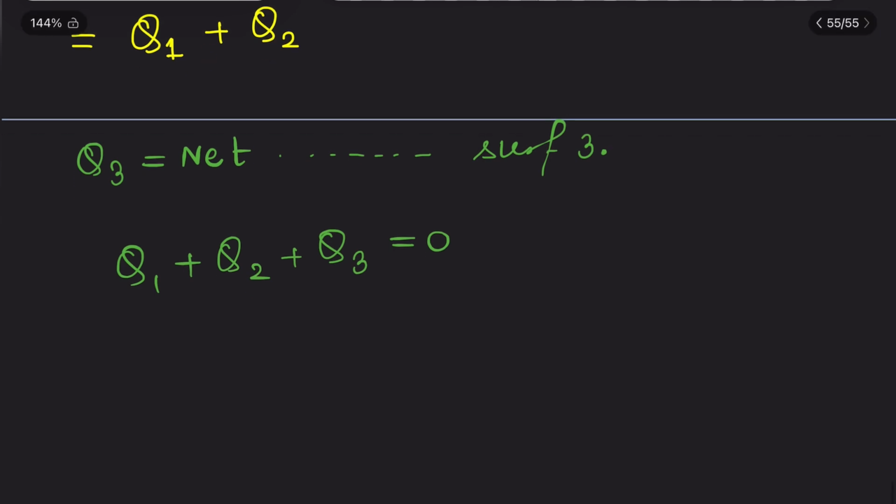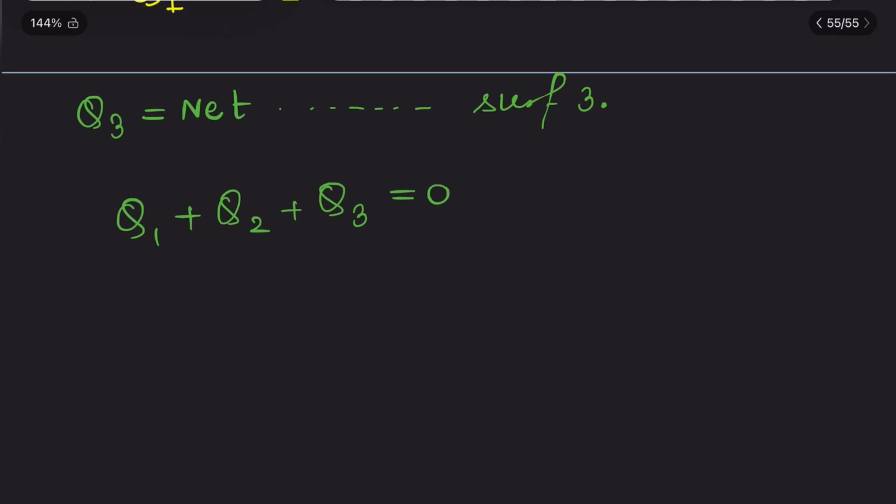Okay, why? Because this is a steady state problem, temperatures cannot change. The temperature of any surface, anywhere, cannot change, and that is why if anything is losing heat inside the enclosure, the other part of the enclosure has to gain that heat. That is why Q1 plus Q2 plus Q3 must be equal to 0. That means if I find Q3 only, then also that will be the answer.